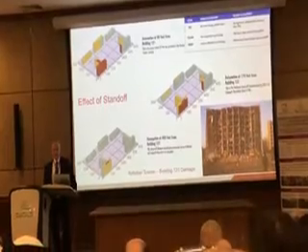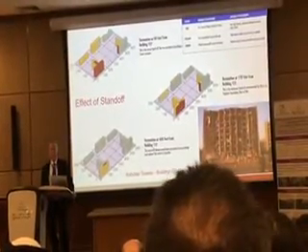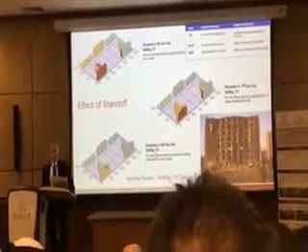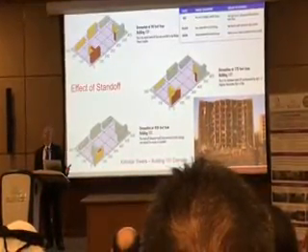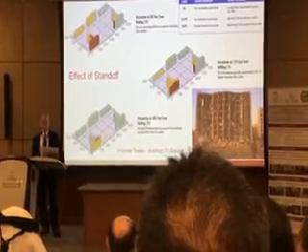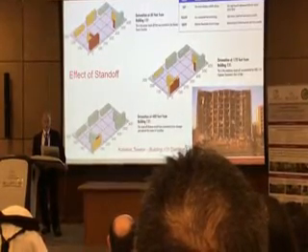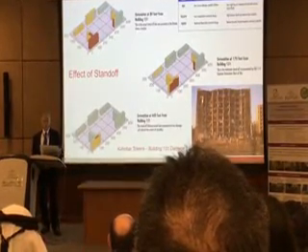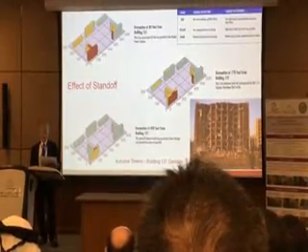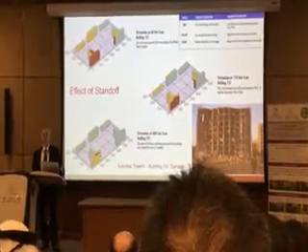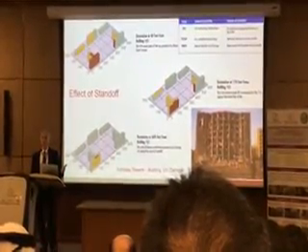Yellow indicates unrepairable damage, and this grayish green indicates possibly repairable damage. The top left shows 80 feet, but if you move away to 170 feet, you see damage is decreasing. If you move to 400 feet, damage is limited to repairable damage.